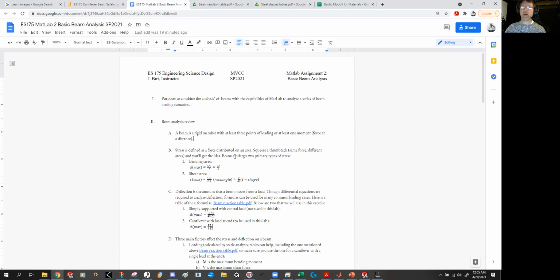Now, stress is a very important concept here. I'm skipping over a whole bunch of stuff, but our maximum bending stress is Mc over I, which is M over S. M is the bending moment, the force times the distance of the bending. S is a function of the beam's geometry. And it's a big difference there.